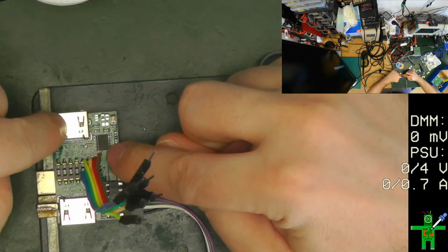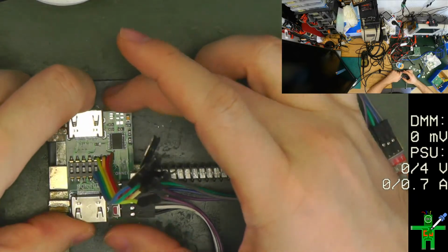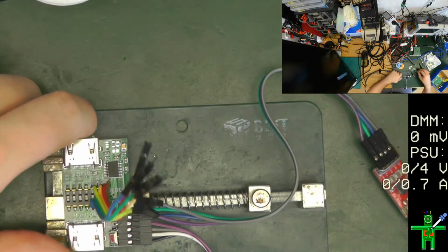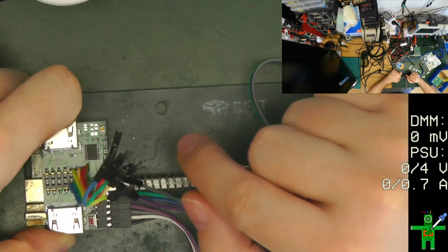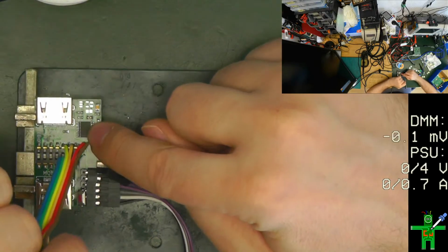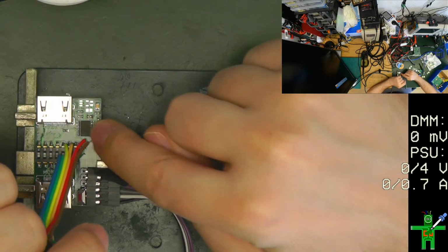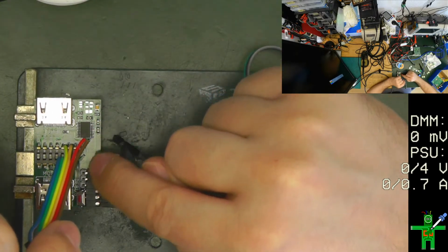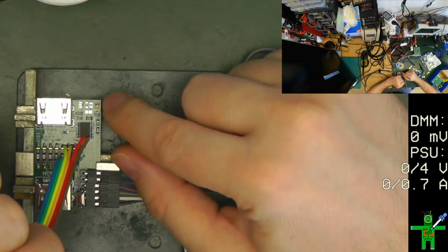So with every HDMI firewall, you can program, you can make a local copy of the EDID information. And actually what I've noticed, that's the third improvement. And this is what I'm currently working on. I did finish the firmware somehow, but I found some bugs. So the firmware here is there, and it can provide the EDID information, and it can read the EDID information from there. So make a local copy, which is not writable, and it limits the interface to the EDID information if you block the DDC interface, so the I2C lines.